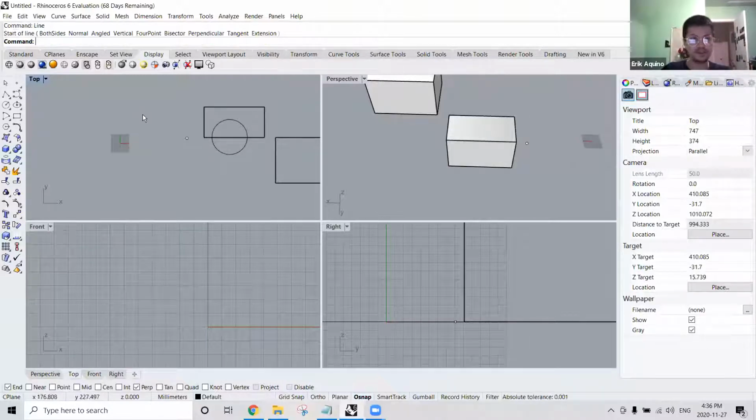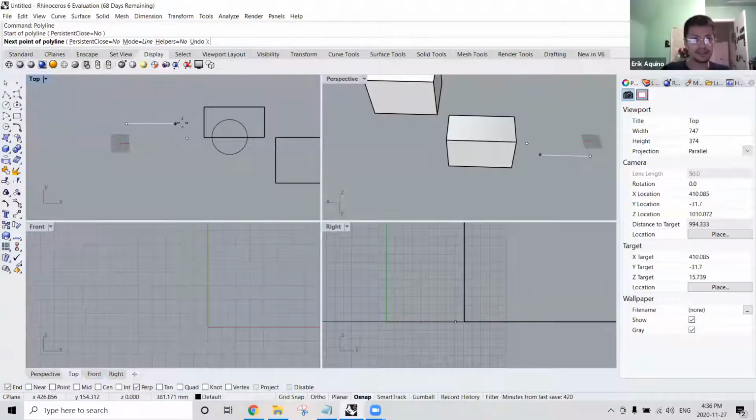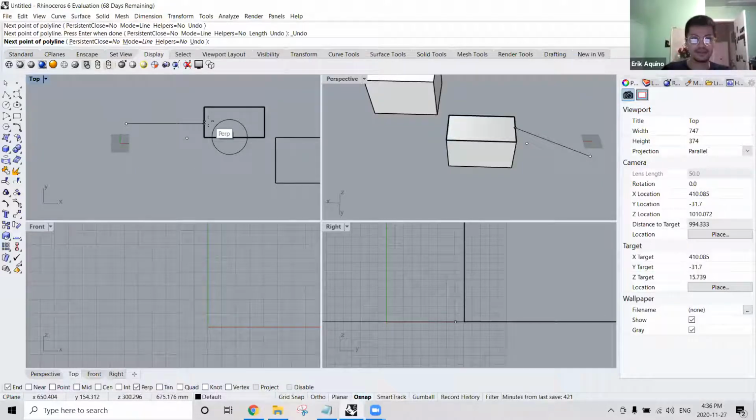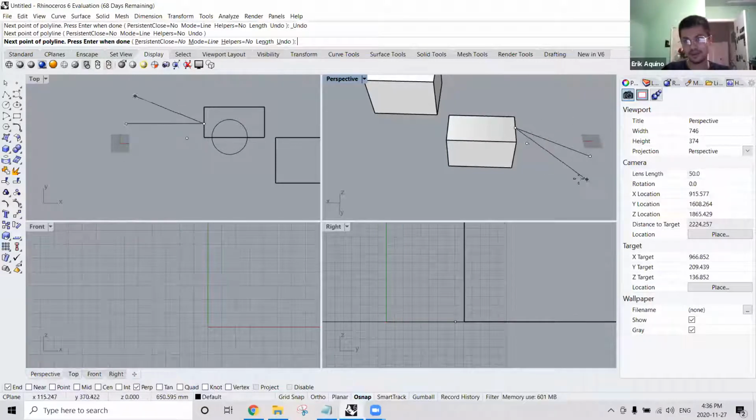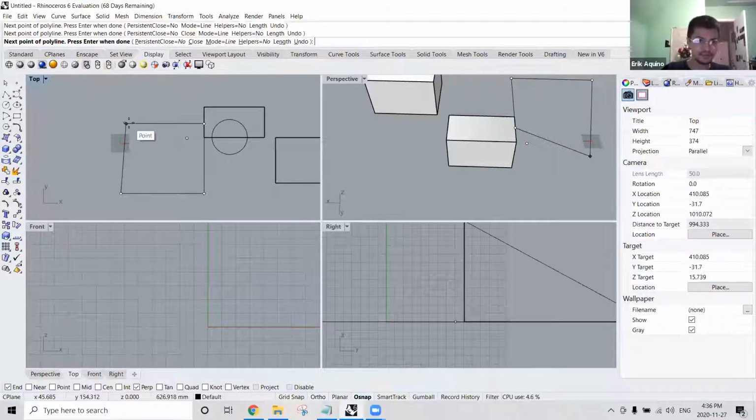And so sometimes if you're drawing a line segment, like a polyline, and end up accidentally using this as a datum to end your line or start a new line, then you'll notice that it might jump up to the top, and that's exactly what happens in a perspective view. But while you're in your top view, it seems fine, right?